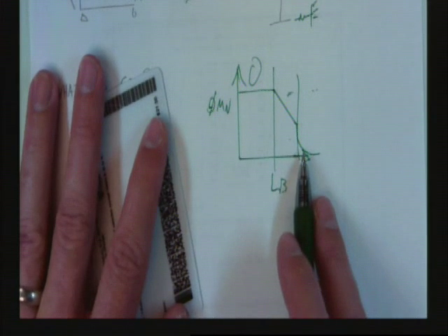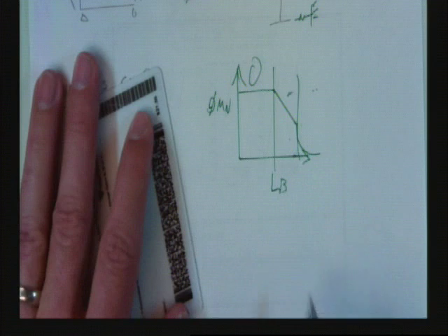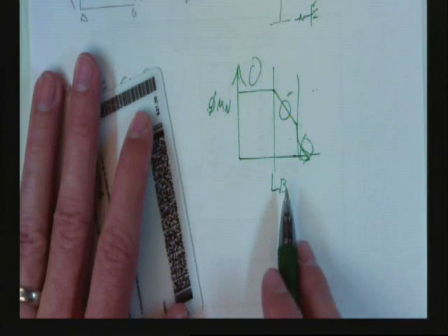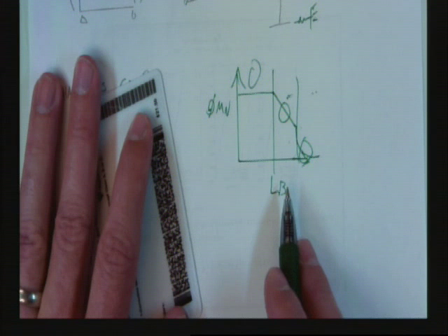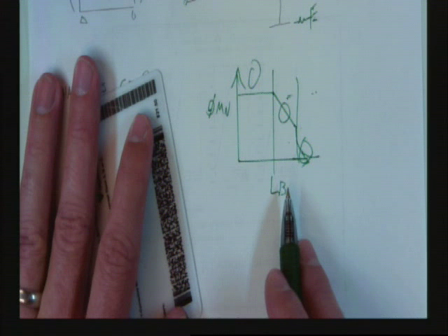What is C_b about? What is it all for? Well, when we derived lateral torsional buckling equations, when we derived those failure modes, we assumed what about the moment? It's constant. We assumed a constant moment. Do we always have constant moments?